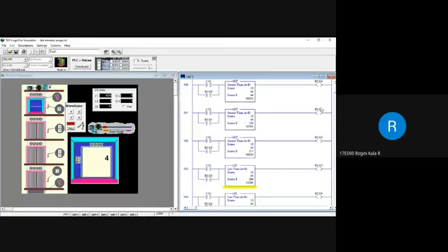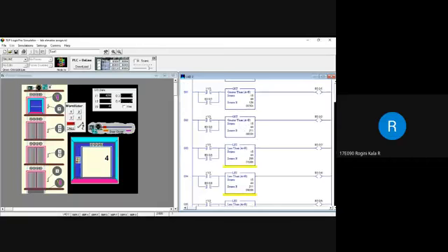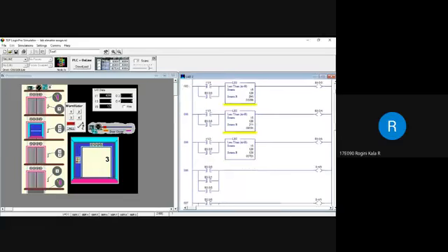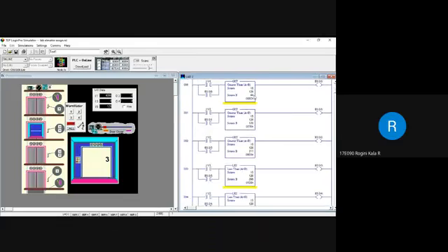The condition is false, so B3:0/1 becomes 0. So automatically O:4/1 becomes 1, and the down motor turns on. On clicking the third position, the down motor makes the lift move downward. It also checks the lesser than symbol and then produces this output.